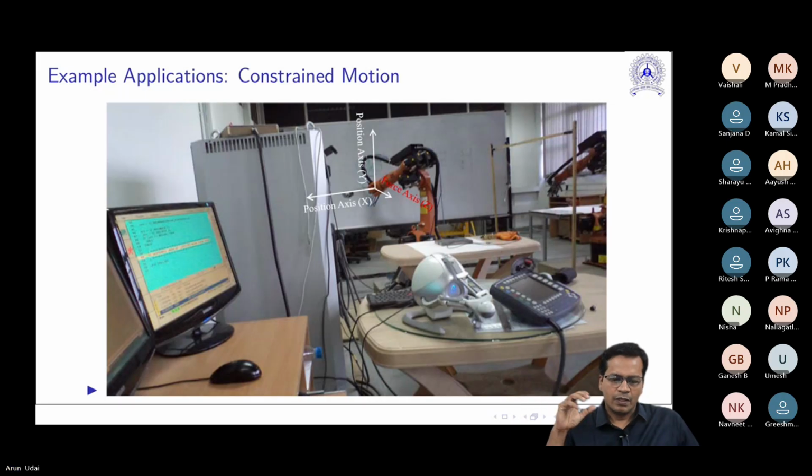So you are locking three different degrees of freedom, you are left with three. Wherever you are constrained, you can create forces because you cannot get into the board. So you can create forces in that direction. If you cannot rotate, that means you can create a moment. If you are free to move, you cannot create any force or a moment, is it not?